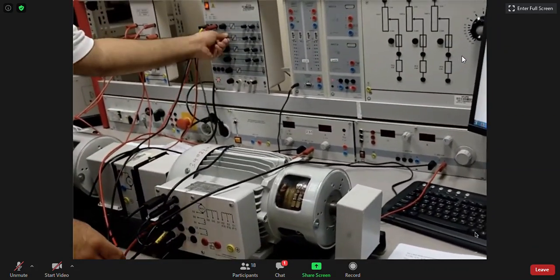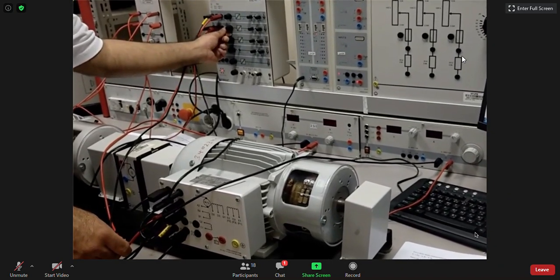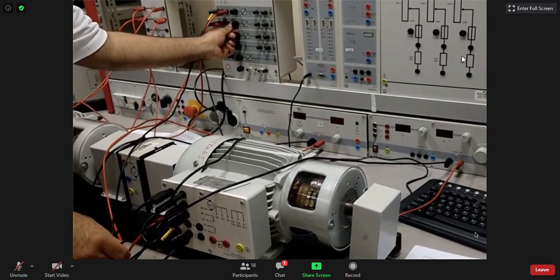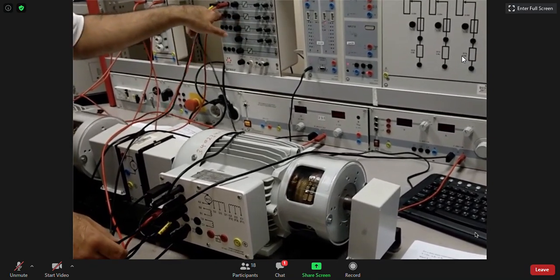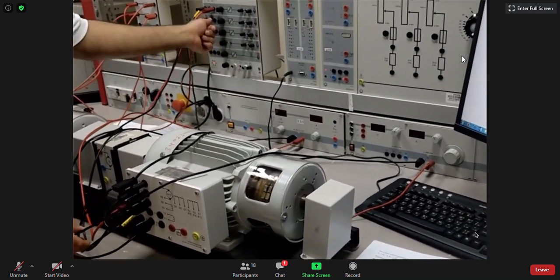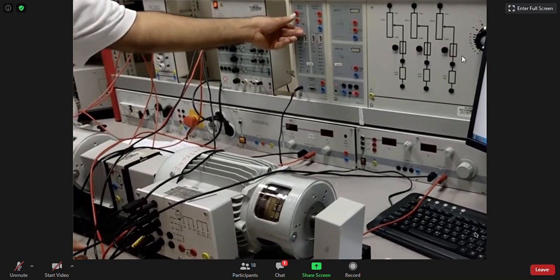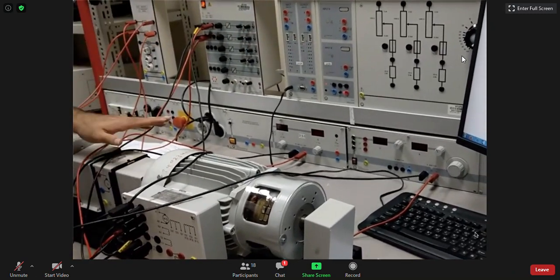Again, as you can remember, when we use this channel as an ammeter, we will select here 1 volt per ampere. What does that mean? Each 1 ampere passing here will be represented as 1 volt here, and 1 volt here represents 1 ampere here. This is the isolation amplifier. This isolation amplifier will be connected to the CASSY sensor and so on. Is it clear?